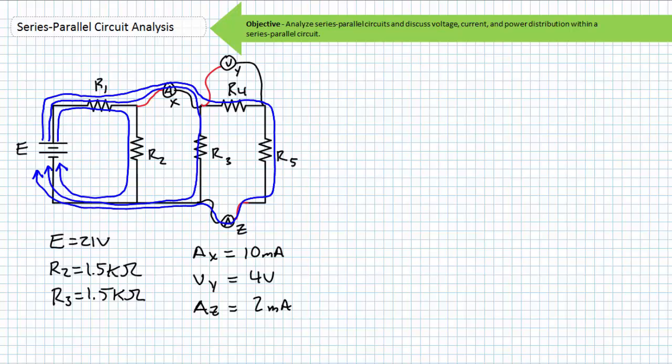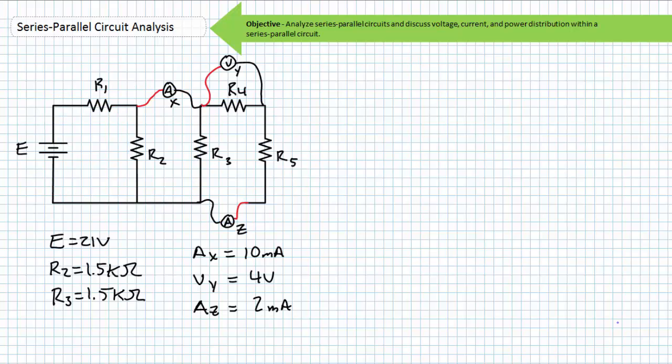If that's not enough, look at the circuit from a nodal level. Voltage across paths hooked in parallel is the same. Think at the nodal level. Remove the ammeters and replace them with short circuits. Ideal ammeters are 0 ohm resistors. Remove the voltmeters. Ideal voltmeters are infinite resistances. Ideally, these instruments don't affect the circuit.